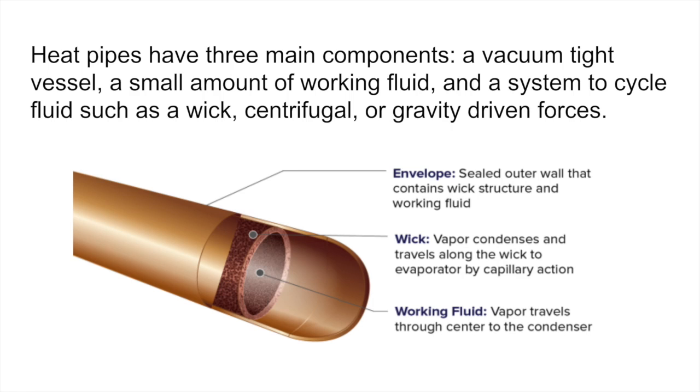The most common heat pipes have a copper envelope with water as the working fluid. Steel and refrigerant are often used in energy recovery operations. Spacecraft often use aluminum and ammonia. Depending on the operating temperature and the amount of heat transfer needed, the envelope and working fluid can be changed to best suit each case.